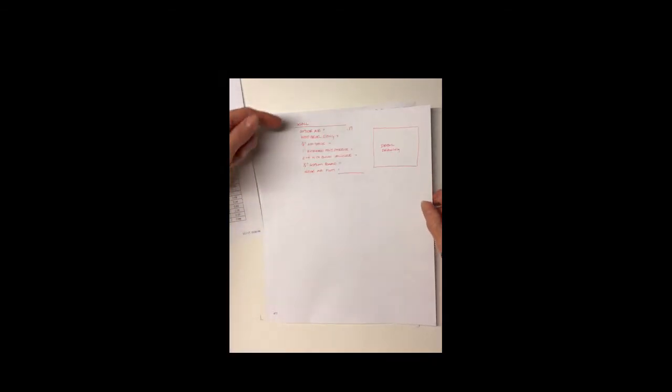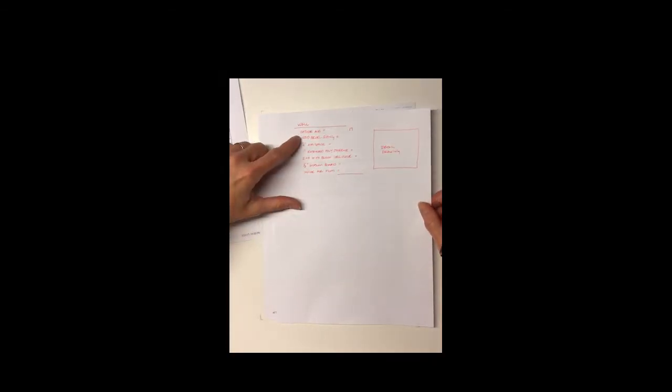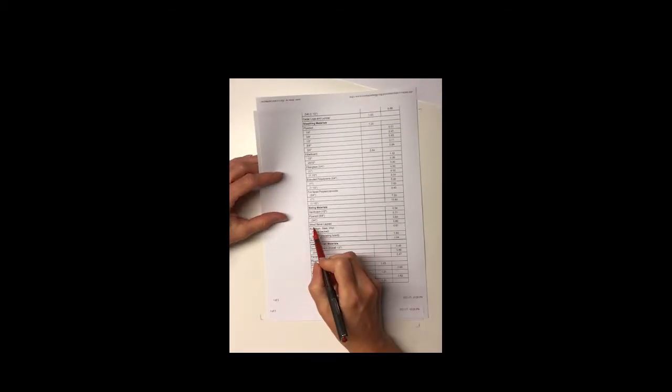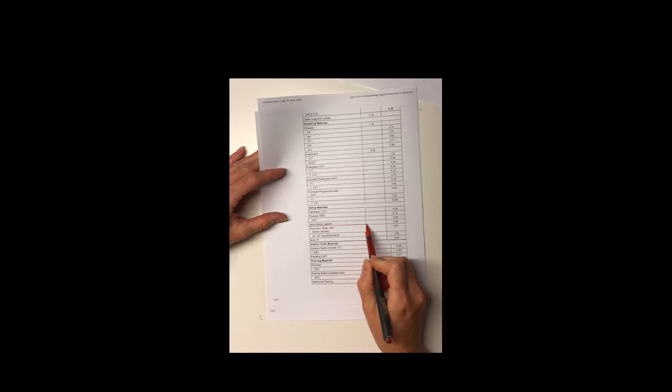For the ceiling, you need to look at the interior ceiling horizontal. And for the inside air, we'll talk about that in a minute. So the next portion that I need to find the R value for would be the wood beveled siding. And so I'm going to go back to that table, and in this case, I'm looking at wood bevel lapped siding.